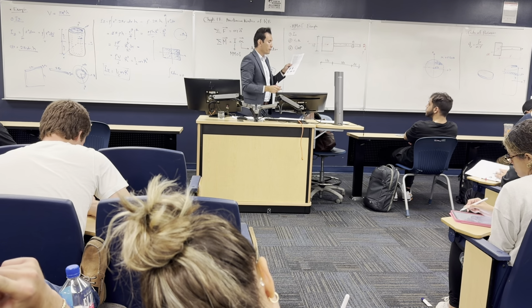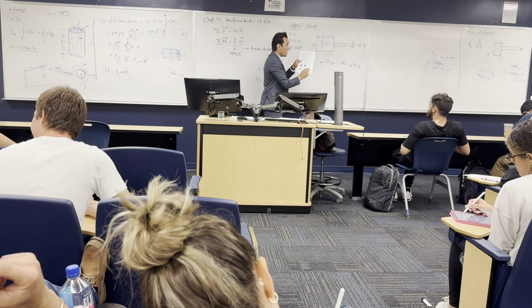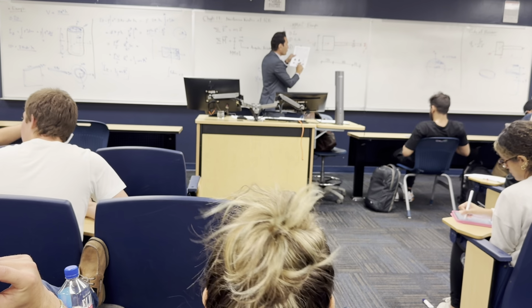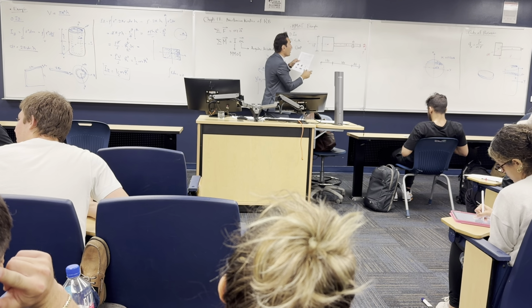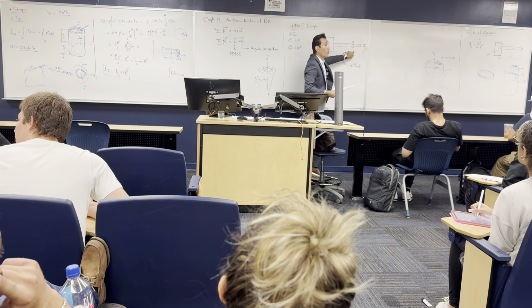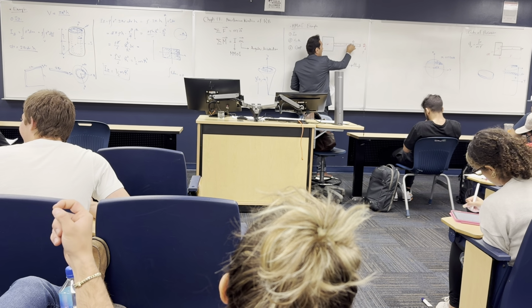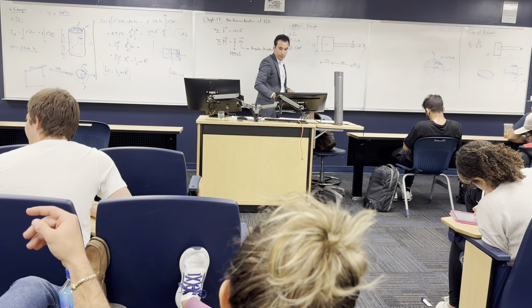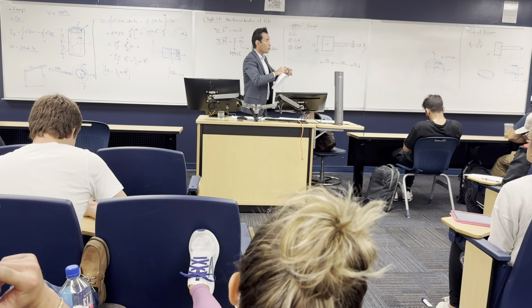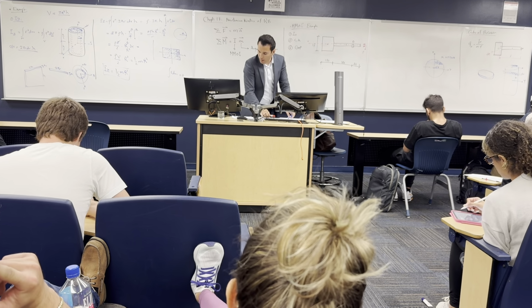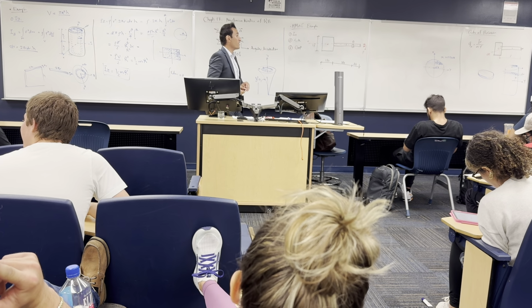Look at the bars and tell me, which one should I use, Ixx, Iyy, to represent I about O? First, I need to find the I CG, and then I transfer it to O. But you need, for sure, to know what axis we are looking at.